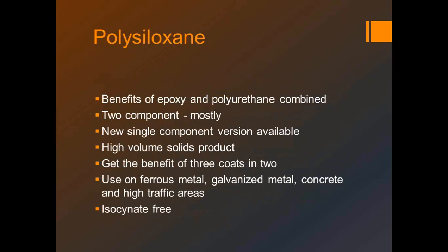That goes along with the whole SSPC systems. That's an absolute minimum. And then we prefer to have either SP2 or SP3 at minimum for some of these things to be able to get them to stick. If we can get some kind of a profile to that surface, the better. Because with any paint system, the better the surface preparation, the longer that system will hold up.